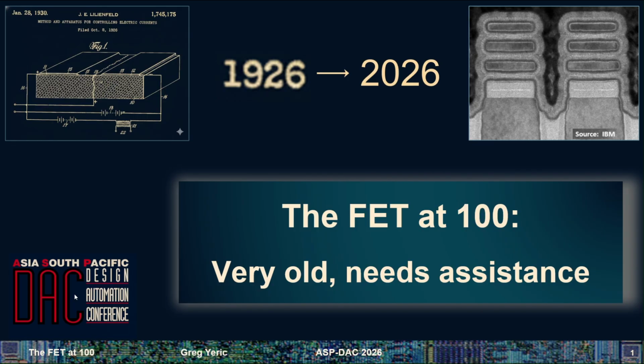Generally speaking, logic is built out of what we call standard cells. So there's software that does the synthesis of your design intent to standard cells, places all the cells, and then routes the wires. So synthesis, place, and route is a big part of the design automation ecosystem, but there's tons of stuff in this conference.